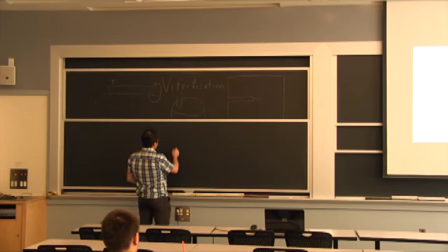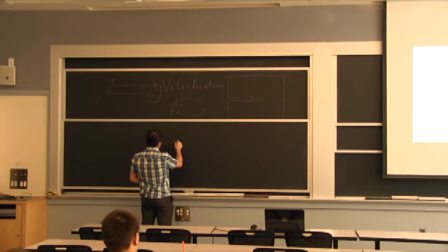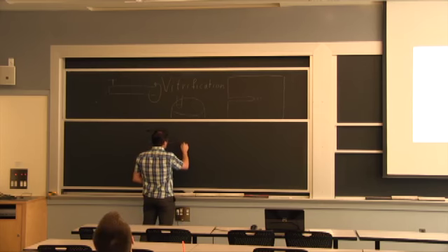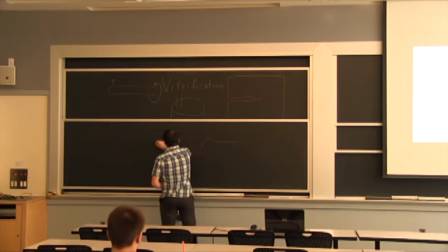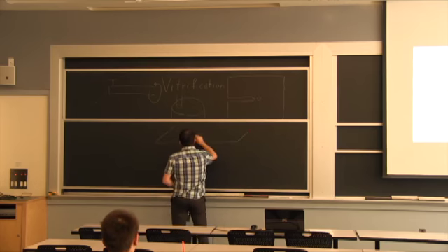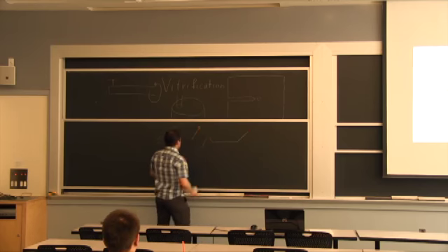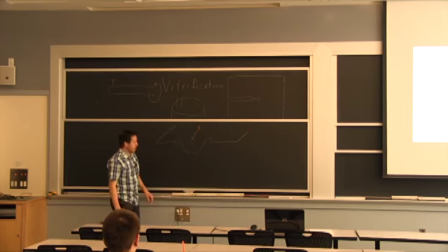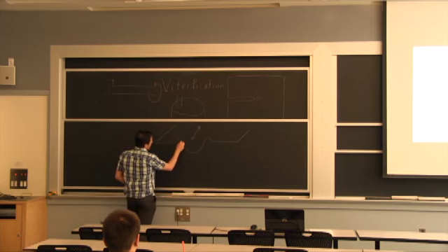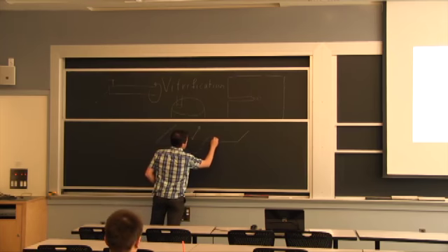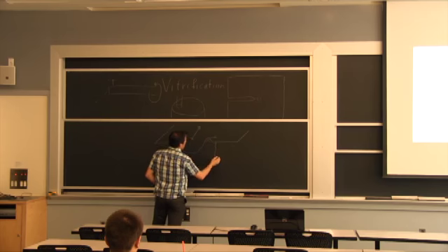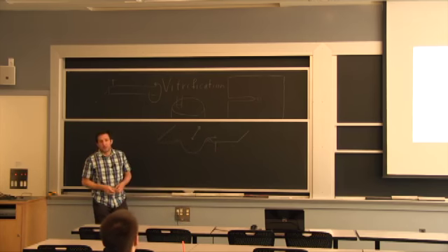say I just do a groove. So I start with a flat surface, and then I come and I plow through. So I'm going to form a ridge here. I'm going to have the hole where my particle is, and then I have another ridge on the other side. So this is for an experiment where I'm essentially displacing a bead in this direction. The amount of pileup we call here, so this material, say we're even looking at it very specifically at the height of it, is very much related to the strain hardening.